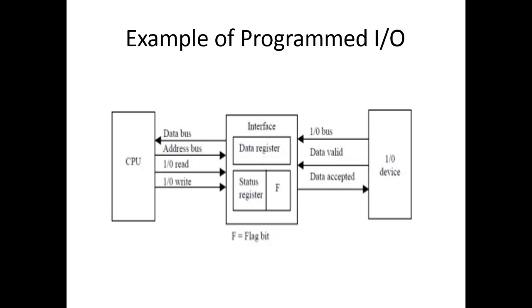To connect the CPU and the I/O interface, data buses, address buses and control buses are used. Here for simplicity, only one data bus, address bus and control bus is used. So let us assume the scenario in which the attached I/O device wants to transfer some information to the CPU, which is required to be forwarded to the memory unit. The I/O device places the data to be given on the I/O bus. The data is first given to the interface.